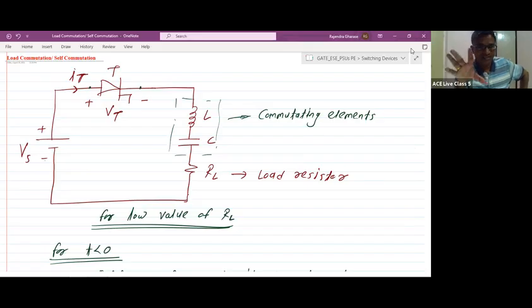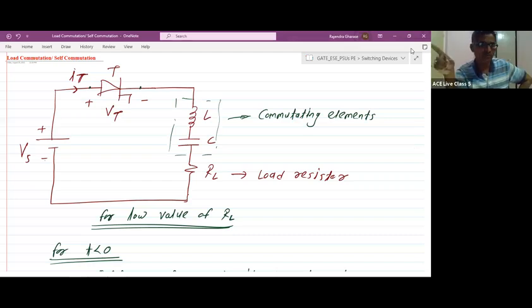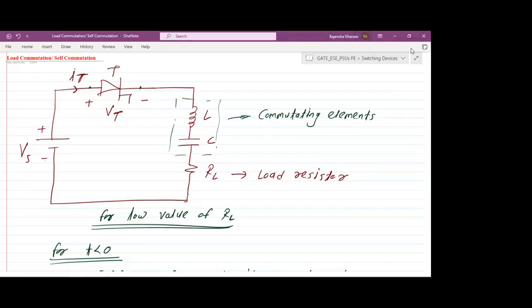First thing is the dynamic characteristics of SCR during turn off. There we have seen that during the dynamic characteristics of SCR, we're having the current decreasing, it reaches the zero value and again it goes into the negative. Yes or no? Yes, sir. What does that negative indicate? Why has the current gone to the negative? Because of the stored added charge carriers. Right? Yes, charge carriers.